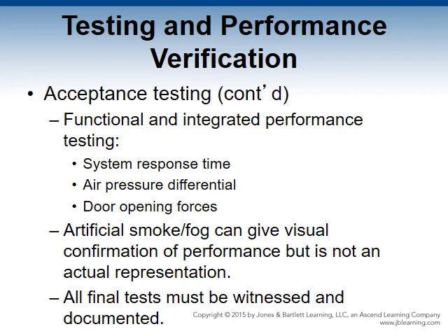If pressure differentials are inconclusive, it is possible to generate an artificial smoke fog for visual confirmation of performance. This is not widely accepted as an actual representation of smoke and gas conditions that would be present once smoke is cooled by a fire suppression system. It may be used to show the amount of time necessary to achieve the acceptable level of visibility through smoke removal in an affected zone.